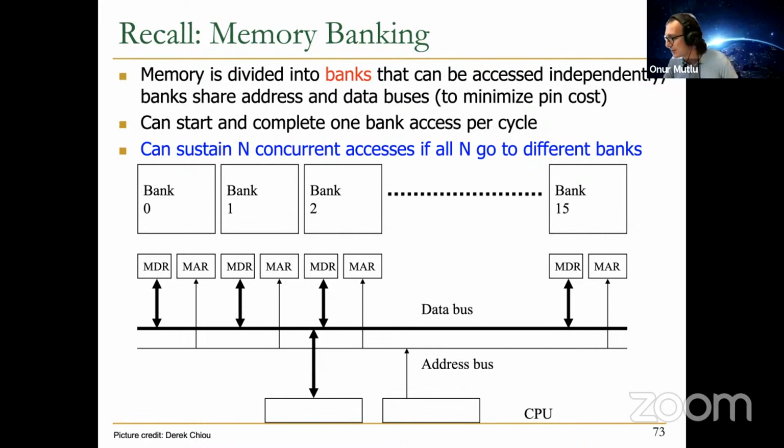Okay, there's one question. Is a certain part of memory reachable only by a certain bank, or is this assigned dynamically? I don't quite understand the question here. So all of the memory is reachable by supplying the bank address, row address and the column address, right? So the memory controller needs to supply which bank you're accessing. And each bank has a partition of the memory, basically.